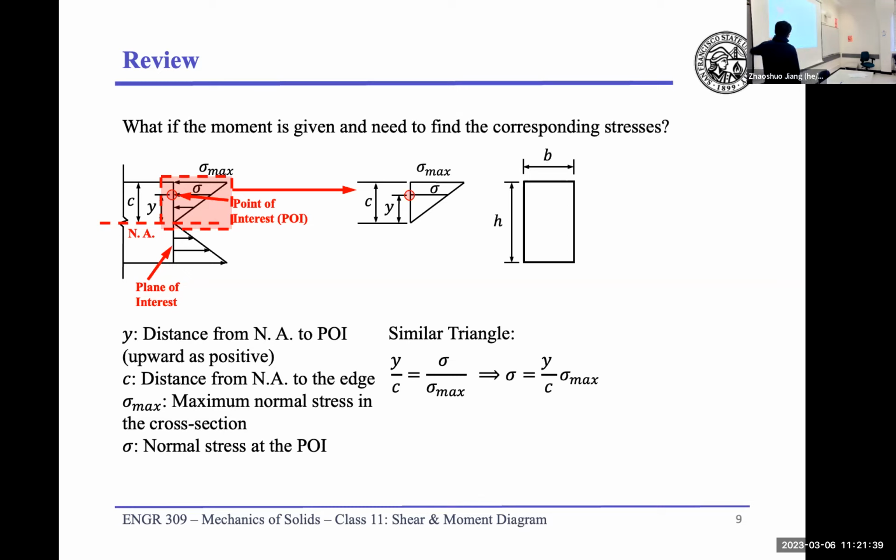Now, if you look at this cross section, meaning that this is a cross section rotated to face you, right? This is our cross section over there. For this cross section, the small area is our dA. The overall force on this cross section is the integral of the force on those small elements of your cross section.